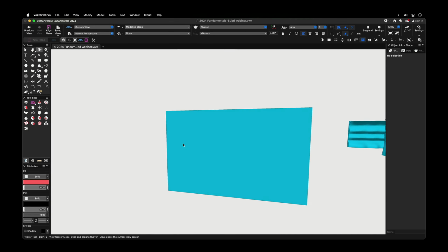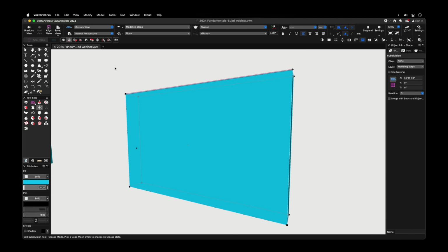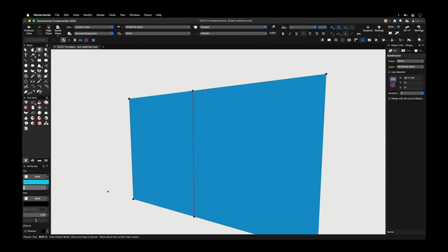For my next step, I'll use a split mode. I'll start touching this edge and type 50 for the percentage. I can also find the middle snap points to divide each face in half, a few times vertically and just a few times horizontally.